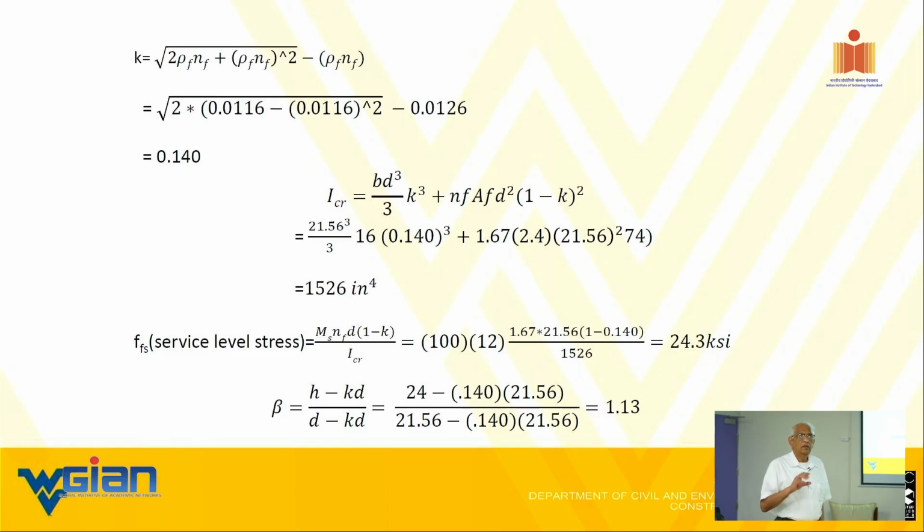And an average number is that I effective, the I value of the cracked section under service load, is about 1/4, 1/5 of I gross value, and the I crack value is about 1/10, 1/12 of it.